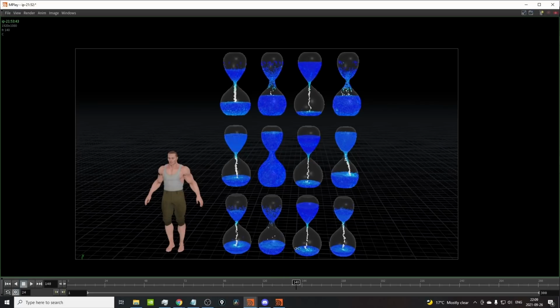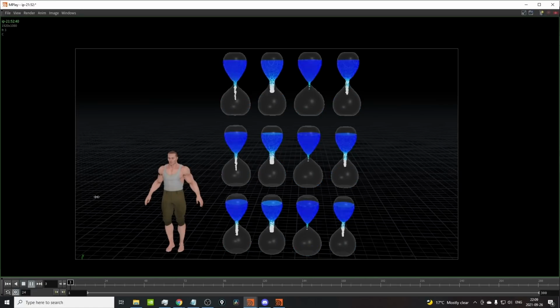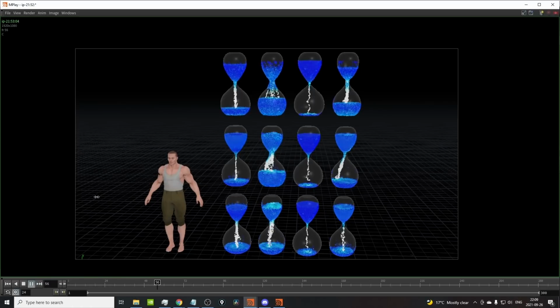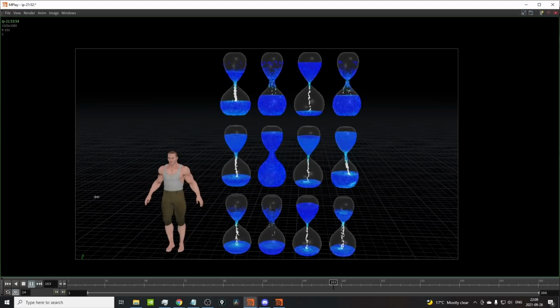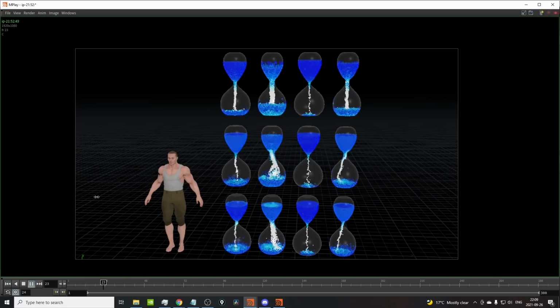And these actually feel relatively okay, but it is very clear in comparison to our standard simulations that the amount of water we're ending up with is now a lot less, right? So that is quite a drastic problem that comes with the air option on the FLIP solver. Now that we know this, we're going to go through and see how that is set up and what some of the conditions are that we need to enable on the solver.